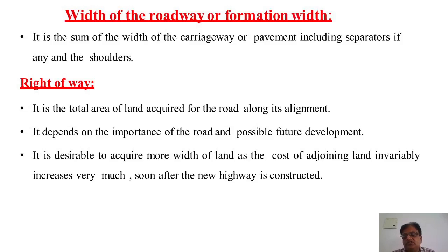So at the later stages you cannot acquire the land. For that purpose it is very essential that you acquire more land at the initial stage itself so that future expansion will be easy. It is desirable to acquire more width of land, as the cost of adjoining land invariably increases as soon as the highway is constructed.